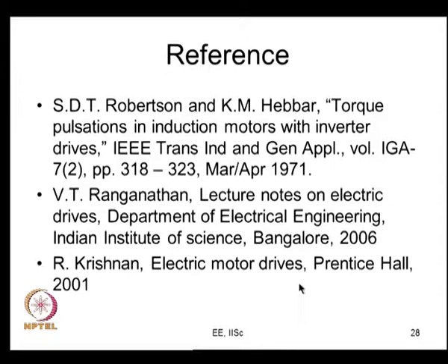We have some interesting papers. It is a very old, seminal paper, original work in this area, and it goes into the details with the per unit equivalent circuit of an induction motor. It is possible for you to calculate how much pulsating torque it is going to produce, for example, when you are fed with a square wave or a particular kind of PWM waveform, and how to calculate the sixth harmonic torque. It is possible to do that using the equivalent circuit of the induction motor. This is one seminal work which explains how to do that.